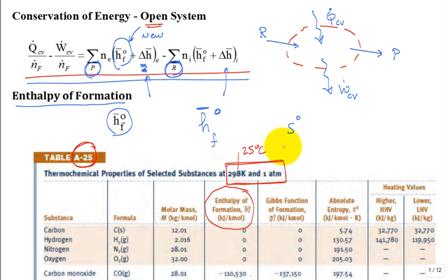Now, we introduced this enthalpy of formation so that we could have the first law where you're actually changing. Think about some carbon, hydrogen, fuel coming in. Maybe it's methane. What do you get coming out in the products? The carbon goes to carbon dioxide. The hydrogen goes to water. So it's rearranging the molecules in the combustion. And that's what makes it essential that we have an enthalpy of formation. Put everything on a level playing field in the energy balance equations.